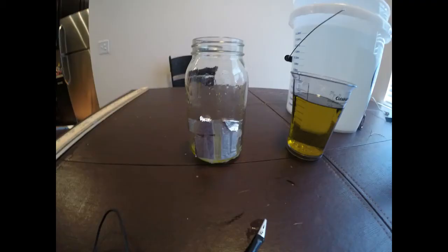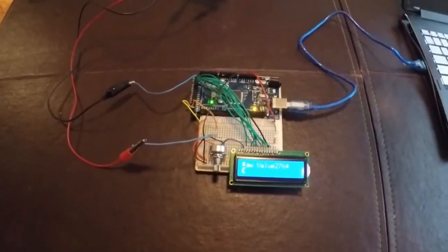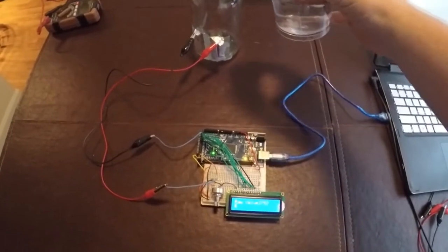The next couple of clips are going to demonstrate the coplanar capacitor, which uses the fringing effect where the electrical field lines will bend in between the plates into the vessel so that the capacitor can actually be on the exterior of the vessel and doesn't have to be submerged. This has been rescaled for this capacitor. I'm going to slowly pour in water.